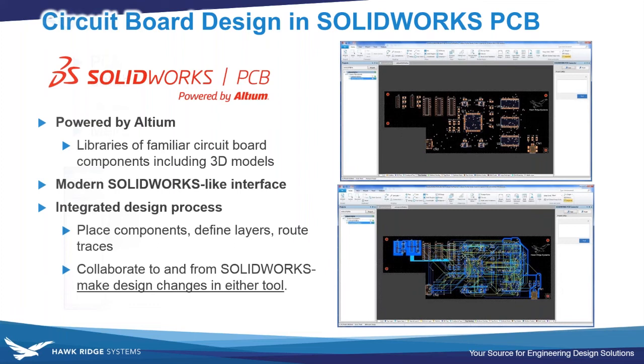But what that means is if you are bringing in a PCB with any of these methods, you're probably going to have a somewhat simplified model of the electrical side, because again, that's not something that you would create from scratch in SOLIDWORKS. And so we need a way to represent what those internal details are, just like you're seeing in those board layout images there, in SOLIDWORKS. We're probably, in most cases, not going to be modeling the internals of a chip or modeling in the solder balls, but we need a way to account for that stuff.